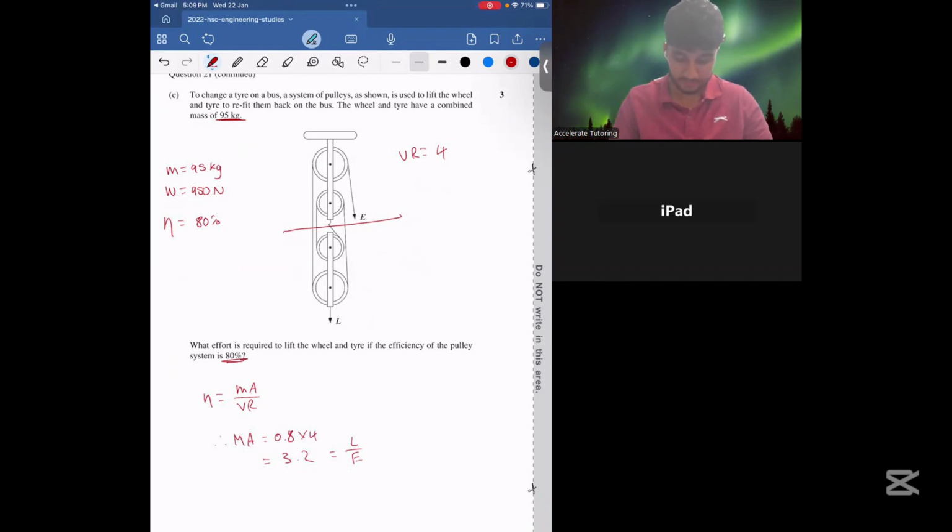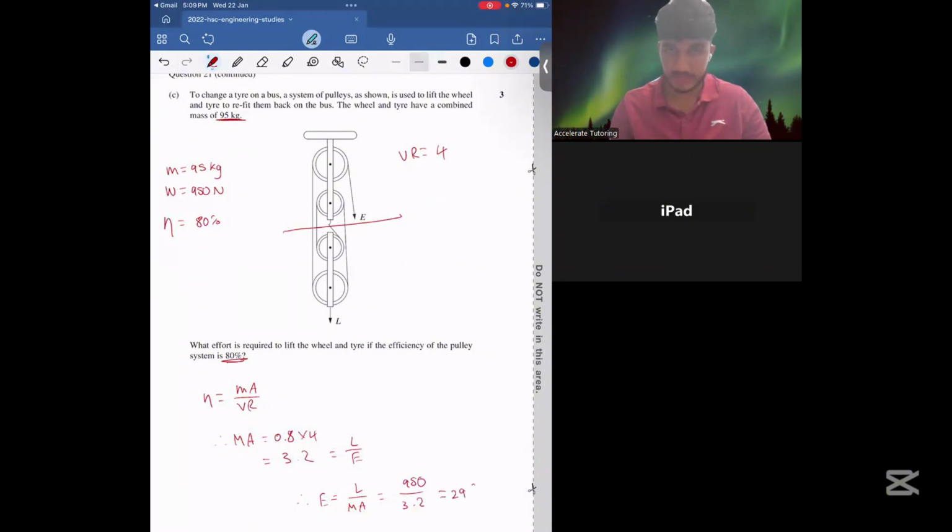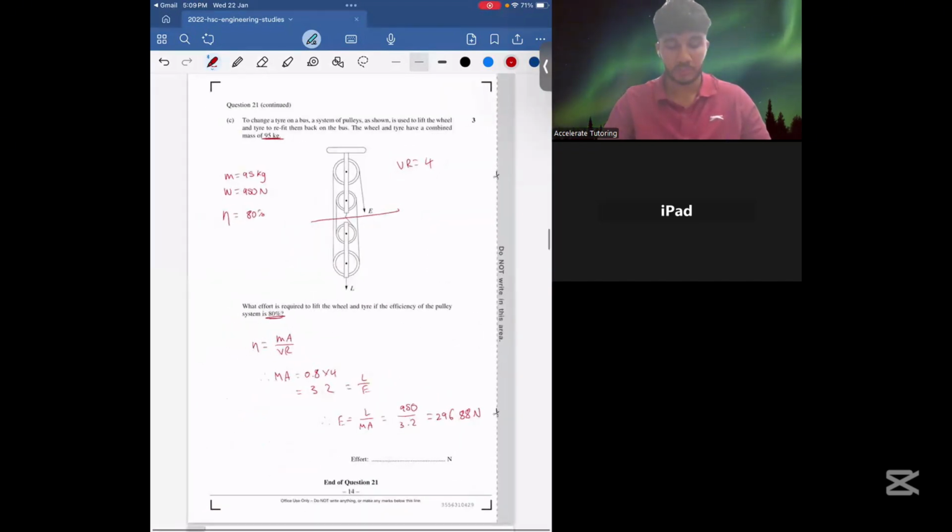That's just 950 newtons. Therefore, our effort is going to be load over mechanical advantage, which is 950 over 3.2. And that gives us 296.88 newtons. That's the answer. Pretty simple. So that's all for question 21. Watch the next video for question 22 of the 2022 HSC exam.